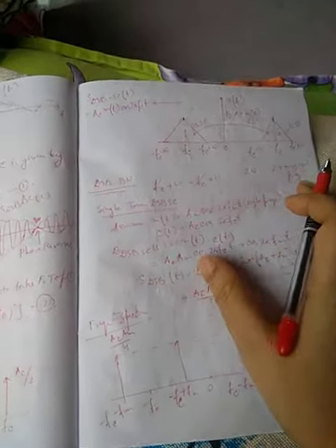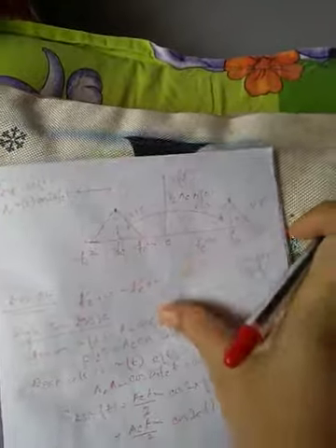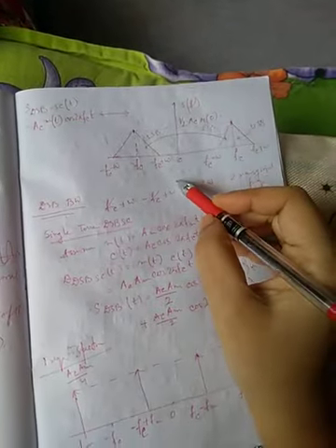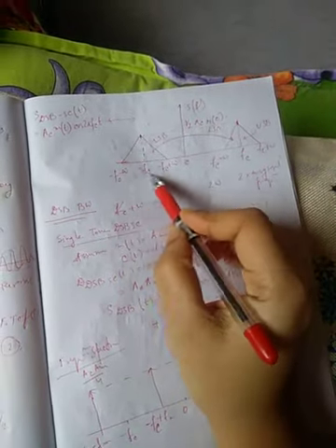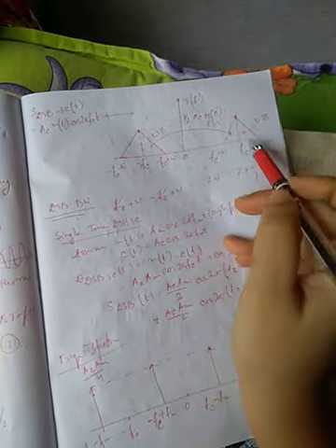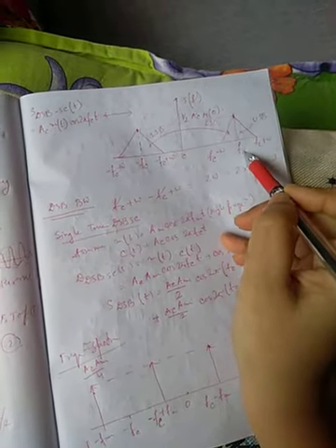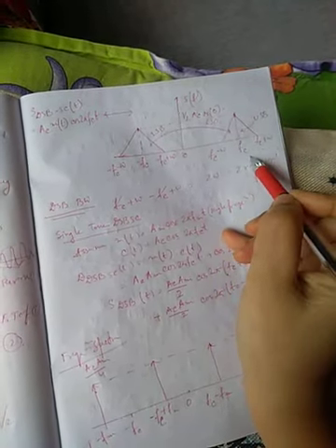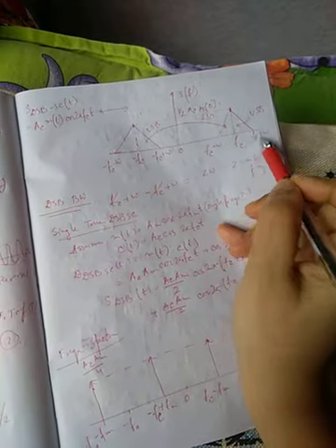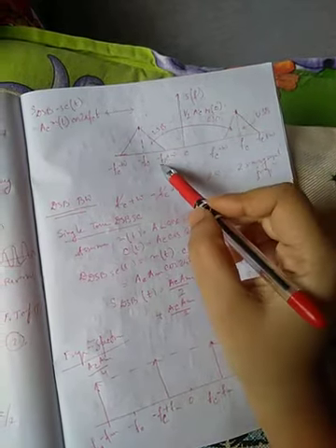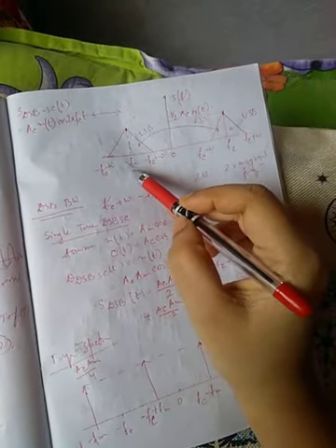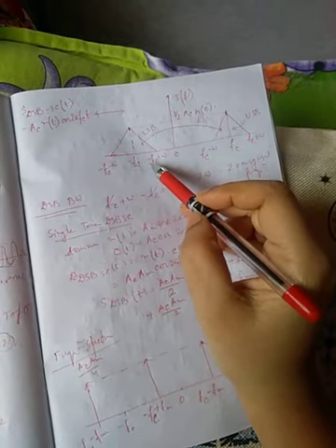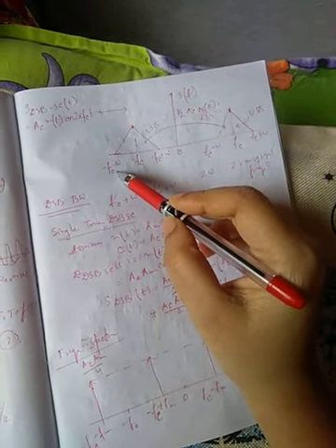So finally I get my double sideband suppressed carrier spectrum this way, where Ac m(t) cos 2πfct, after the Fourier transform, gives both sidebands. This is fc, and the two sidebands, fc plus omega and fc minus omega, are centered around fc. On the negative side, the mirror image is created around minus fc: minus fc plus omega and minus fc minus omega.